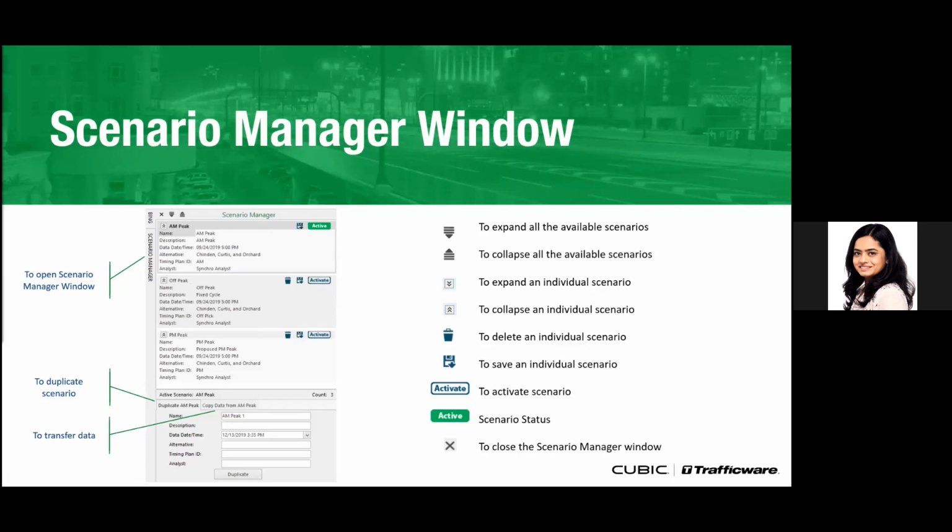That would happen, right? Like you are working in a large group and maybe you are agency people, your consultant didn't actually upgrade it to the 11 or vice versa. And maybe they're planning to do it, but right now you have a project deadline and you want to finish it. And the other group still need that Synchro 10 version because they didn't upgrade it yet. So you can actually use that save scenario button and save down to 10 and then send them back.